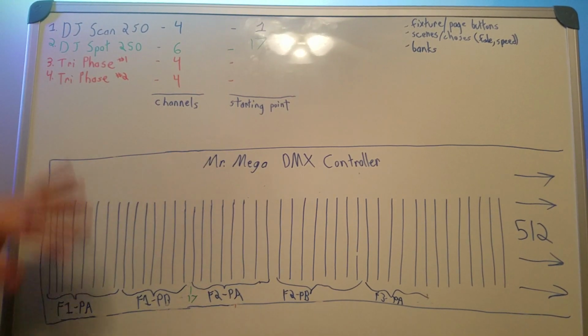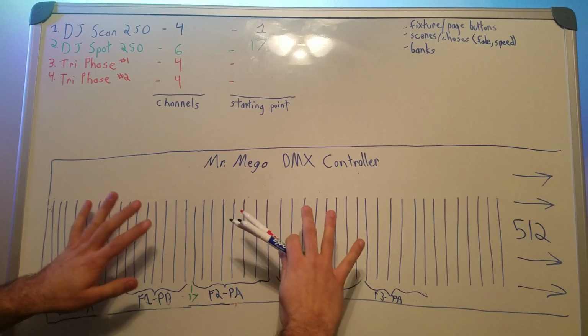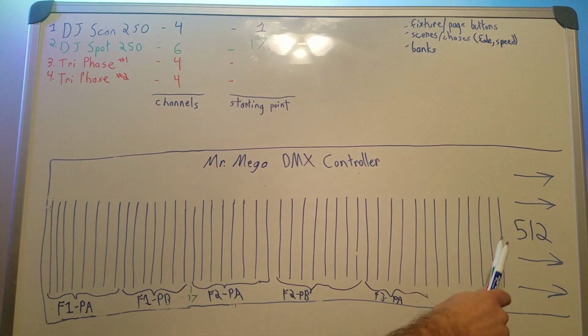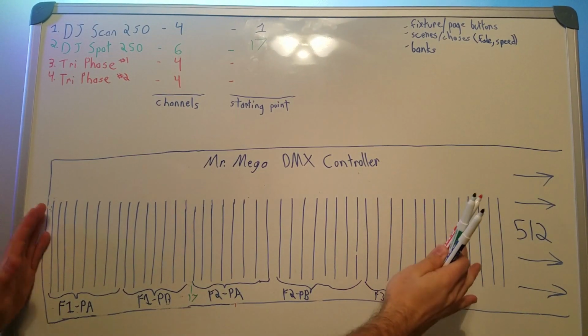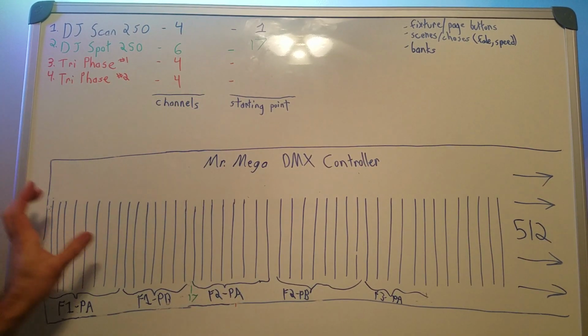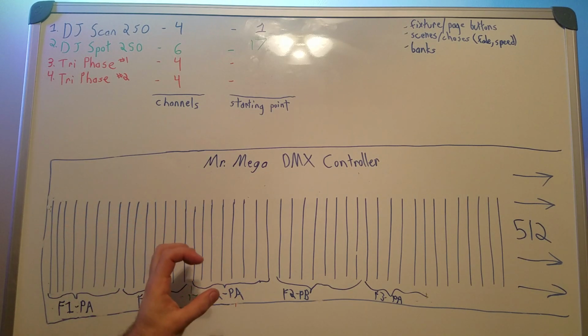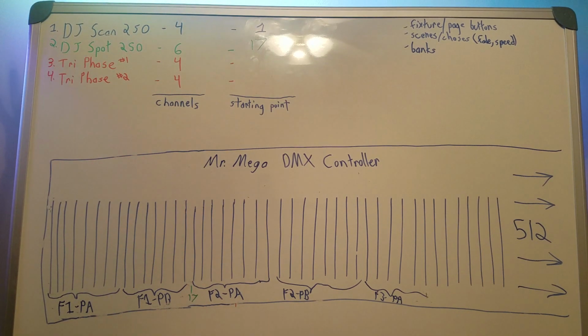The controller is going to put out information for, I put 512, my controller does 192 specifically. So my controller will put out signal for 192 channels, and then whichever lights are programmed to identify information from specific channels, they're going to register and broadcast out. My controller does not care what the lights are doing out there.